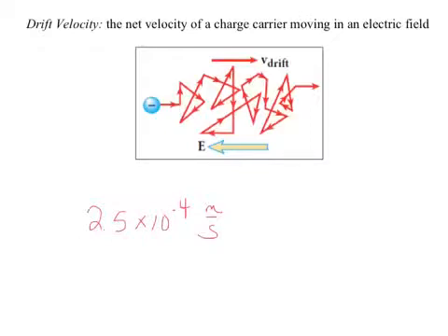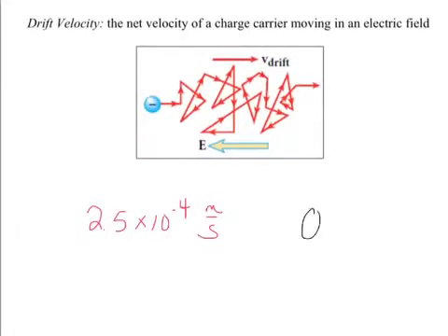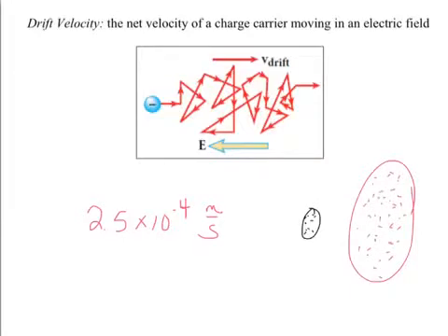In this case, we're looking at the amount of charge carriers or electrons that cross a given cross-section. So if I have a really small cross-section, only a few electrons might be able to pass through here or whatever it is, right? But if I have a much larger cross-section, then there are many of these that can cross in a given time period. So they don't have to be moving fast as long as there are many, many of them moving across a given area in a given time period. That's what current really is. It's not really the speed, but it's how many move across a given area in a time period. And again, this cross-section of the wire here shows how this works differently. The current here is much higher than this current, for sure.